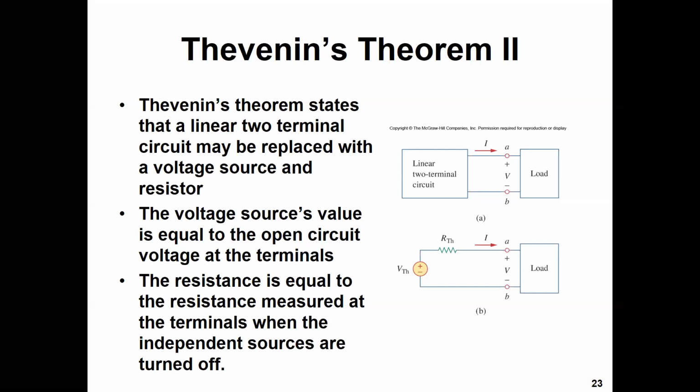So if we use Thevenin one time, we don't need to analyze the circuit every time we change the load. And this is the beauty and the benefit of using Thevenin theorem.